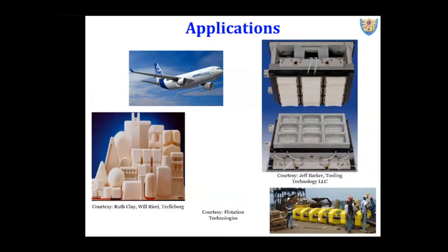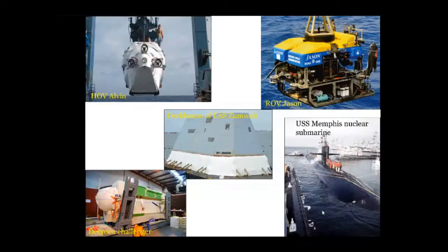And thereby, these pipes are roped into these yellow modules, which you can see down the line here. These are known as flotation modules. When you put these in, the total density goes much below 1, and thereby the pipe is floated on the water, and we are reducing that rupture phenomenon. And this material is not new. It is a very old system. Only how these are manufactured and synthesized, based on advanced technology, the routes are changing.